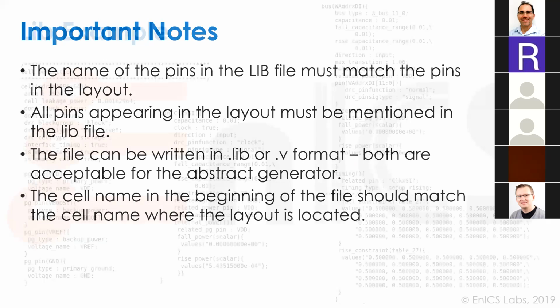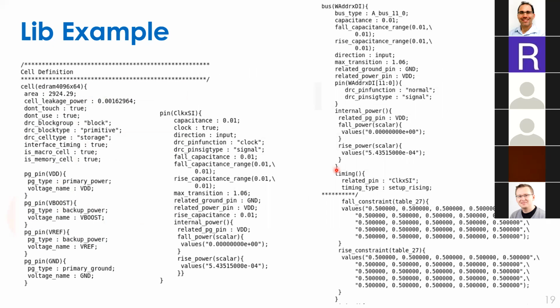One more comment. I think that the lib file has actually a huge header that you don't show in here. So the lib defines the default process node, the default corner, a lot of tables like 5 on 5, 6 on 6, a lot of stuff that you don't show in here. It's right. Yes, exactly. Here it's only a cell, but the lib file has a big header. Yes, exactly. It has a lot of other parameters there, and I just wrote to myself to add it here so I can show it.